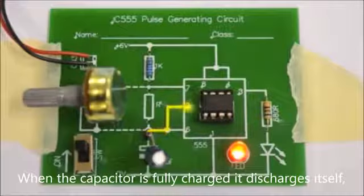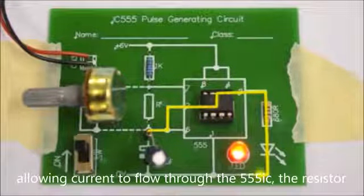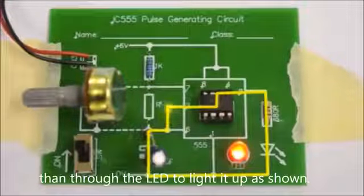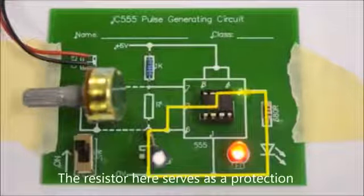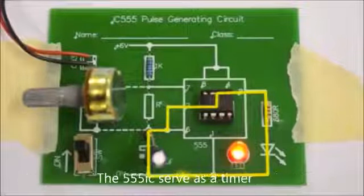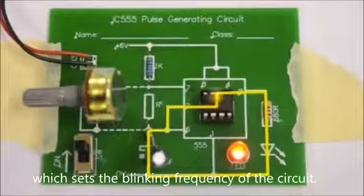When the capacitor is fully charged, it discharges itself, allowing current to flow through the 555 IC, the resistor, then through the LED to light it up, as shown. The resistor here serves as a protection to prevent large current from damaging the LED. The 555 IC serves as a timer, which sets the blinking frequency of the circuit.